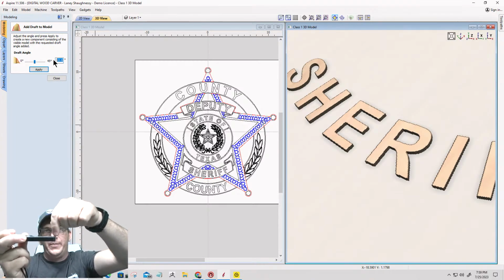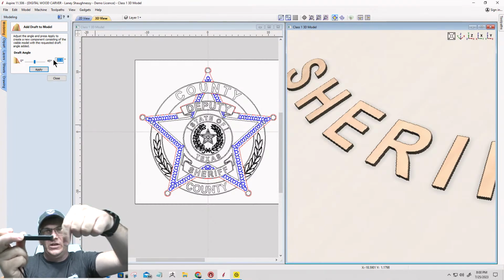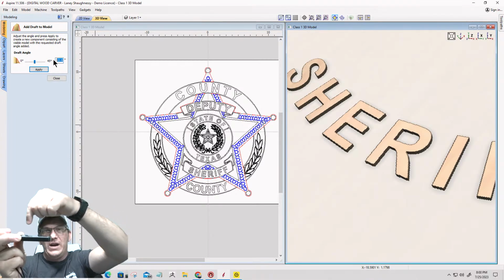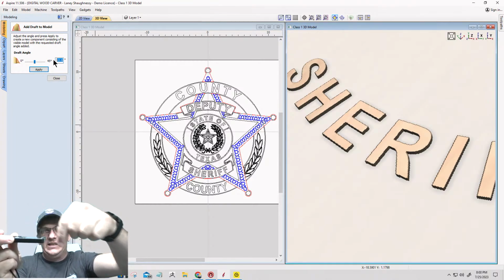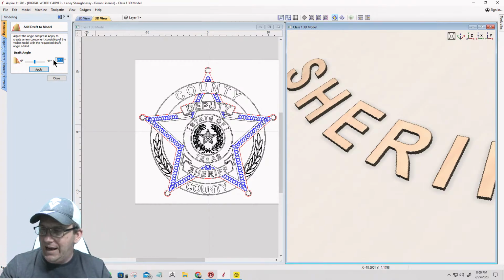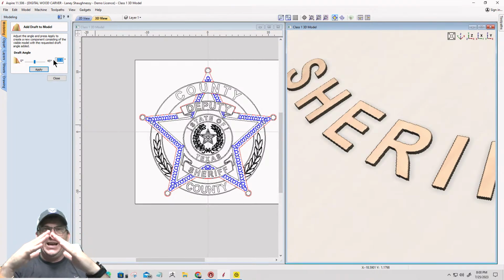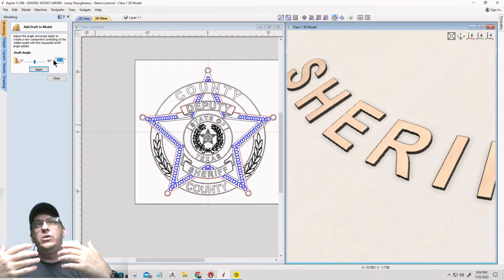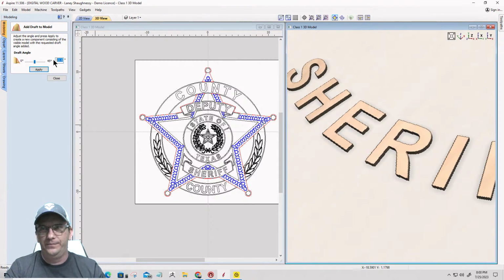Instead of dropping off the ledge on a straight edge and slowing down to pick up, when it's creating that 3D model, I want it to just ramp, so it doesn't have to decelerate that much. So adding the draft, one, gives me a little bit of edge meat, but it also helps me with doing the little things that I can do. And in the grand scheme of things, it is little things that we're doing to optimize runtime.